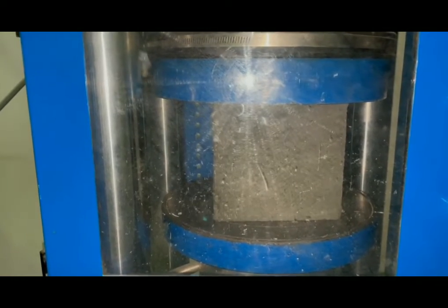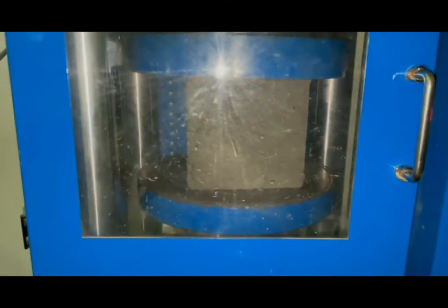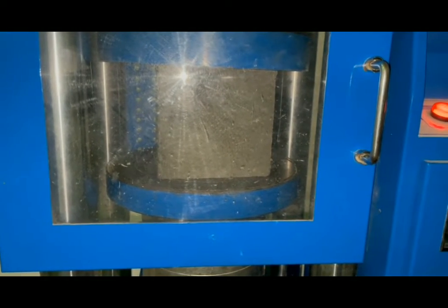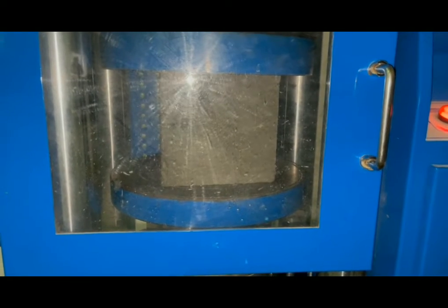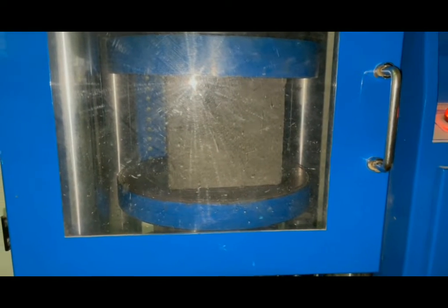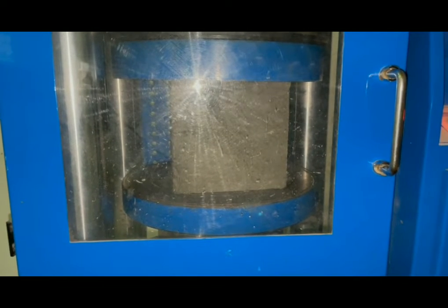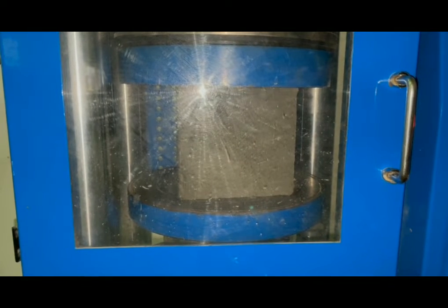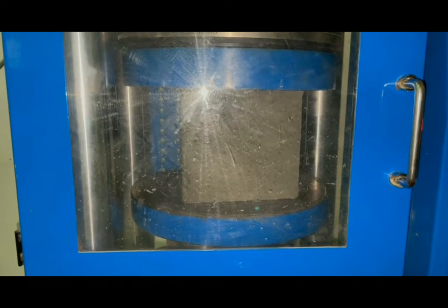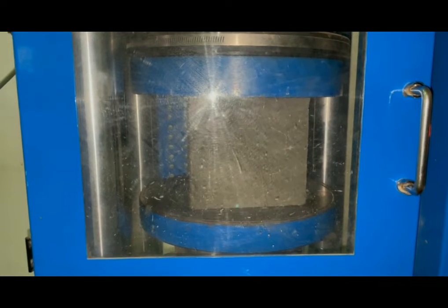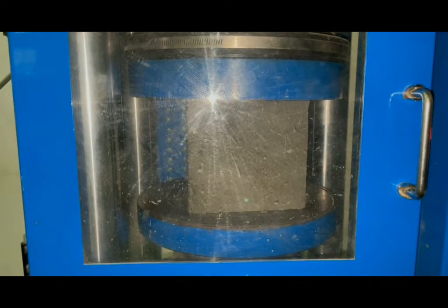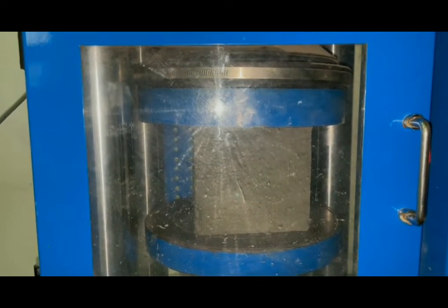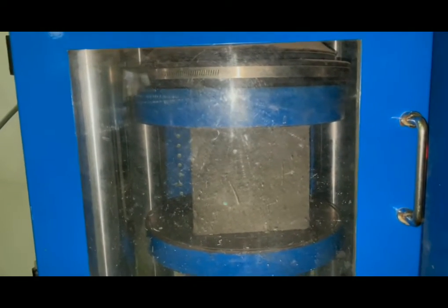The movable portion was rotated gently by hand so that it touched the top surface of the concrete. The run button on the compressive machine was pushed and load was applied gradually without shock and continuously until the concrete failed. All the data was recorded. Repeat the steps on another labeled concrete, and on 2 labeled concrete after 28 days.